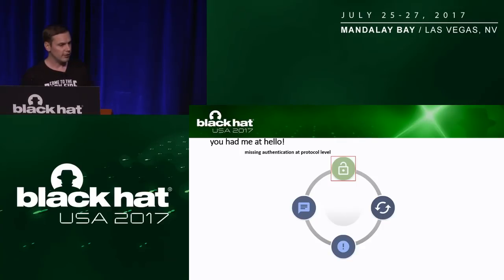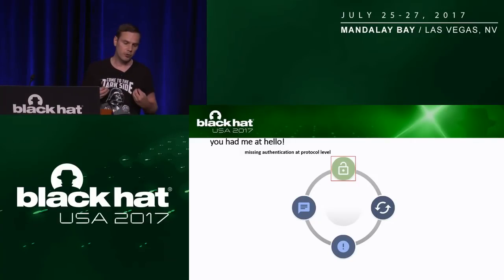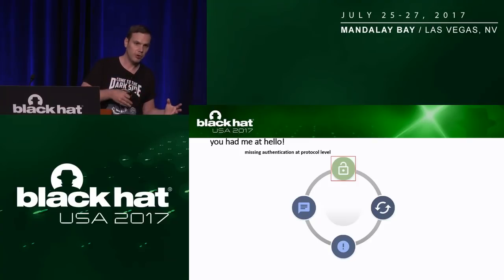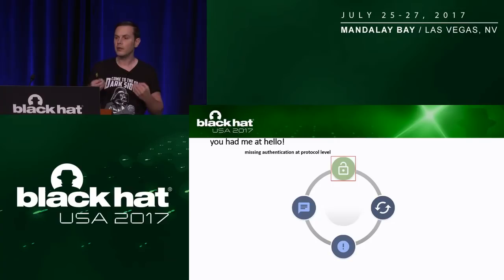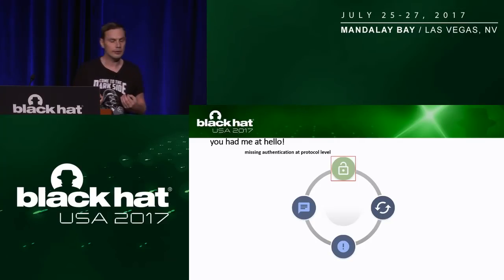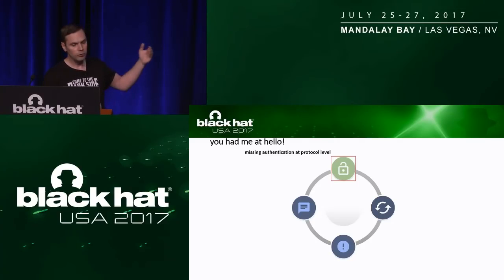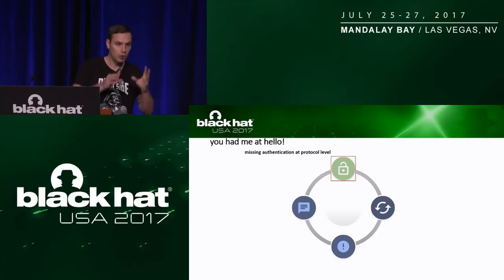Basically, the message here is I'm talking about native security functions in building automation control. I guess we have pretty much the same situation that we had in ICS security in generic industrial control systems, like missing security by design from the very beginning, also in building automation control, because those systems have been designed as maybe locked-down, closed systems that never were meant to actually be connected to open networks.